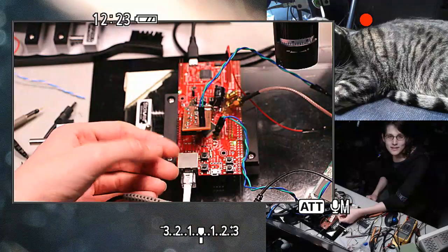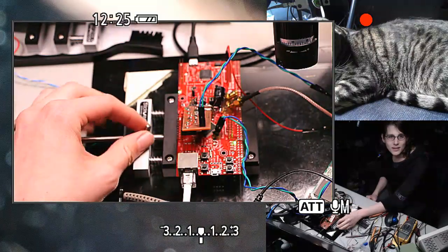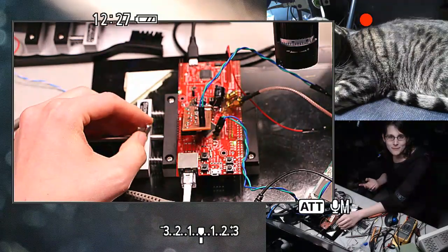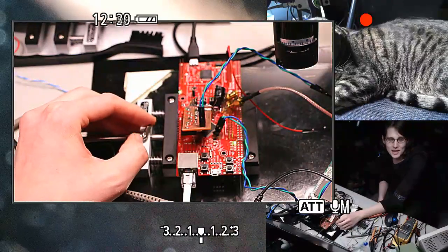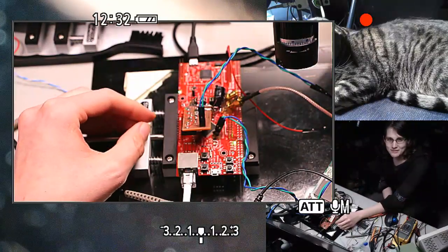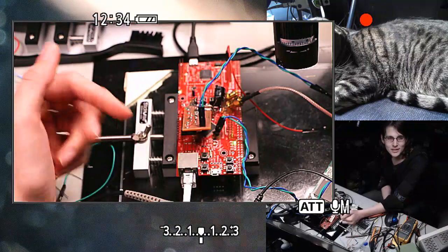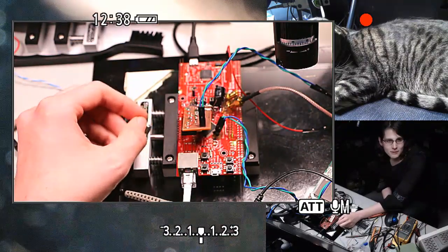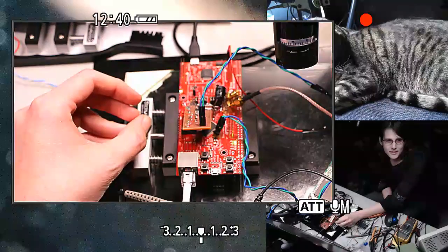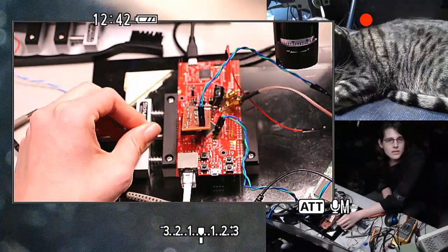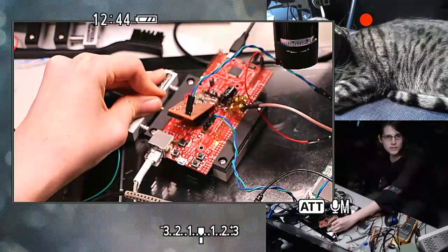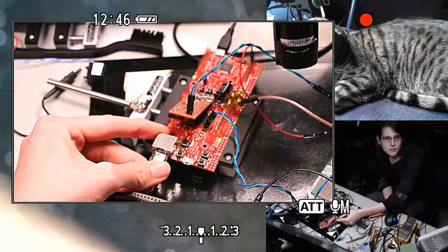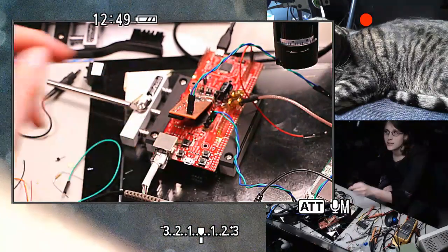It also helps that TI apparently designed their PHYs to decently tolerate being capacitively coupled, whereas there isn't really a clear way to capacitively couple the ENC28J60 without it becoming kind of a pain to interface with. So yeah, my current plan is when I resume this to just start working on another one of these boards.